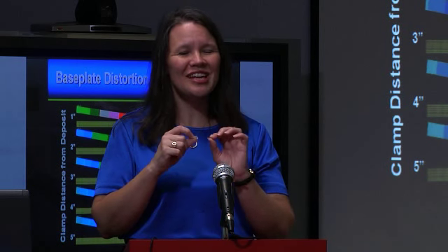So if you're focused on distortion, that's one thing, but stresses are sneaky little guys that you really want to be careful of, because if you've got a lot of residual stresses and you load a part up like on an airplane, that stress acts on top of whatever load you put on that, and so you can start to induce cracks in a structure much earlier than you would expect if you've got high residual stresses. So you want to be real careful and make sure that your stresses don't get too high. Does that make sense? I can explain it later if you want.